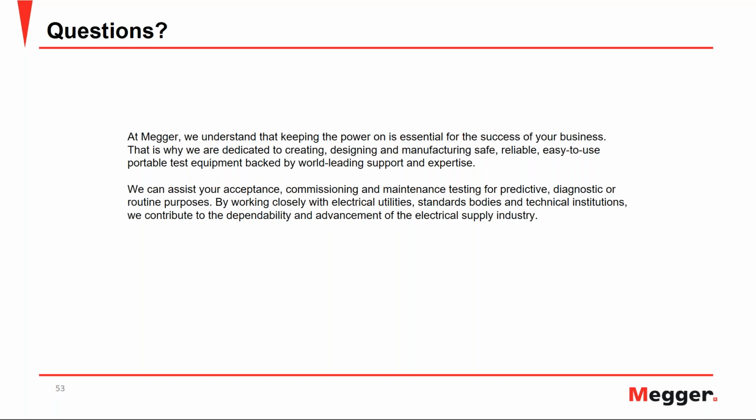Then we need more tools for investigation. Power factor test sets now can have that additional investigation tool. So without moving into other testing, you have a way to investigate the insulation right there on the spot while you are testing, without waiting for a couple of days for oil results.